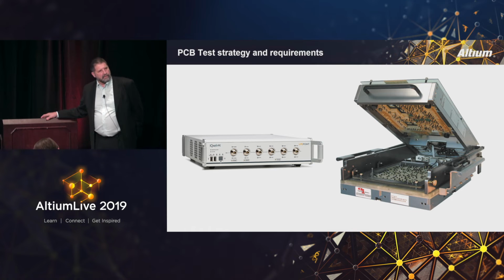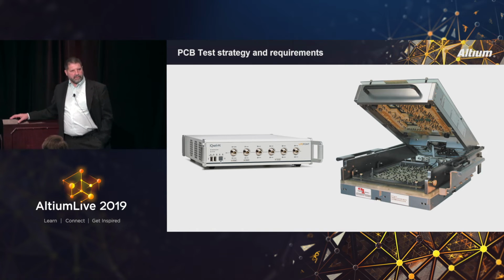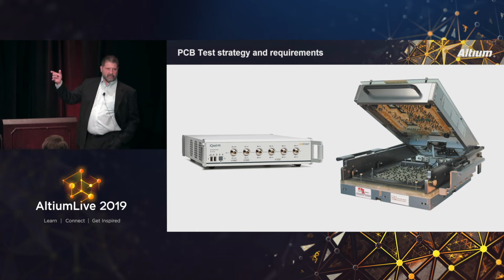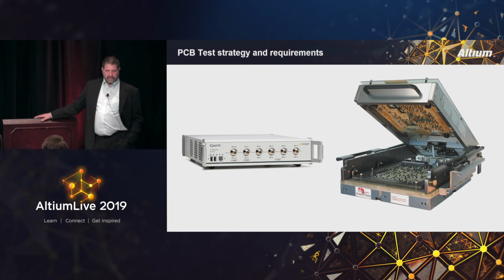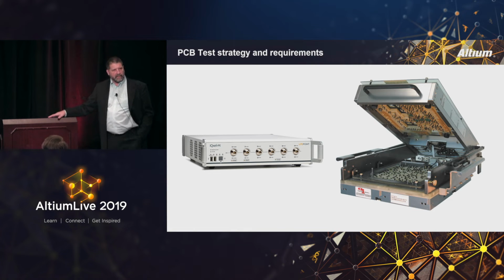Yes, absolutely. So when you use a via, you want to make sure that that via is not tented or encroached, but make it larger on the test side. If you want to save a little bit of room, you can build a custom pad stack that might have like 25 on the top, and then it might be like a 20 or a 16 on the bottom, depending on the hole size.